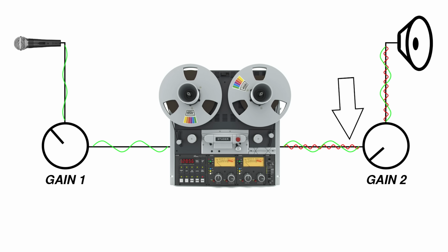To avoid overdriving the tape machine, you're careful not to turn the signal up too loud, but you should also consider what might happen if the signal is too quiet. The tape has a certain level of inherent noise of its own. The tape noise stays the same no matter how high or low you set the mic preamp. If you record a very weak signal to the tape, the signal-to-noise ratio will be very small.